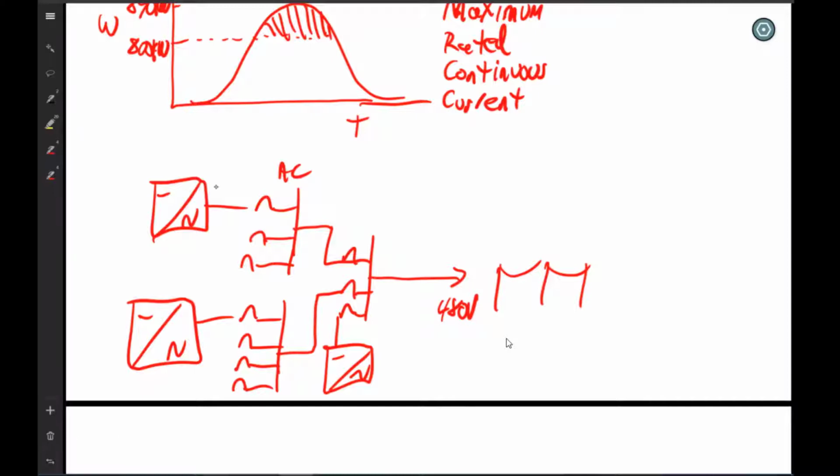Now, we have a certain voltage drop on this point, which is Ohm's law, V equals IR. So you have that 72.2 amps, for instance, if these are assumed to be 60 kW. And then you have a wire size and you have voltage drop.